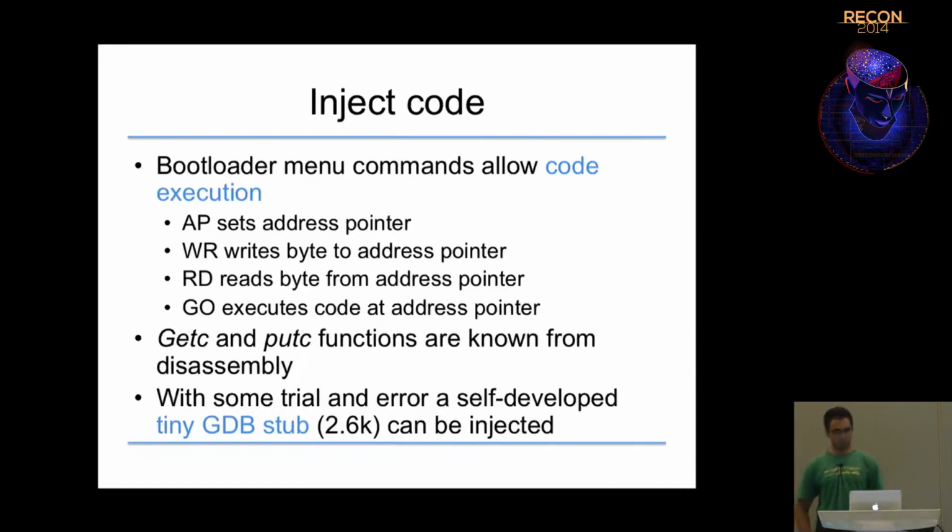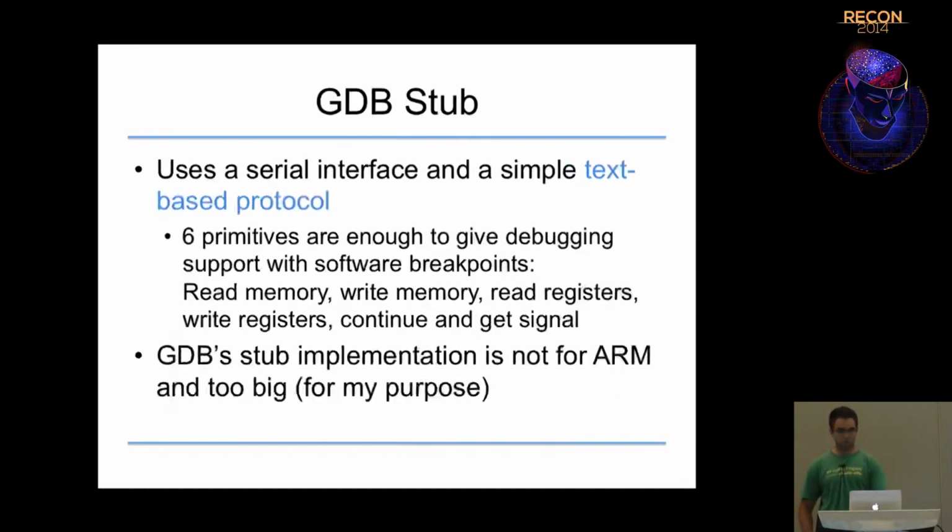And this led to the development of a tiny GDB stub that then can be injected through this bootloader menu, which I wanted to use to debug the firmware later.